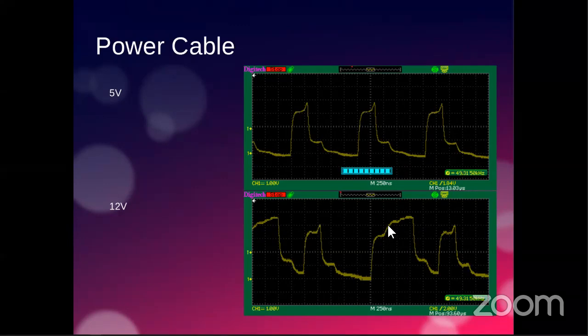So the time between here and probably roughly here had better be long enough for this to be read as a 1, or this is going to be erroneously read as a 0. There's a risk here if this voltage falls at all that this won't be read as anything at all as well, particularly if the voltage starts to degrade. So yeah, you end up with quite a different shaped signal or timing of signal. There's your 1 and there's your 0 on those signals.